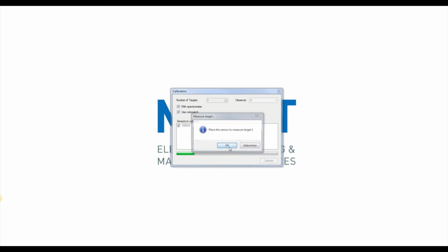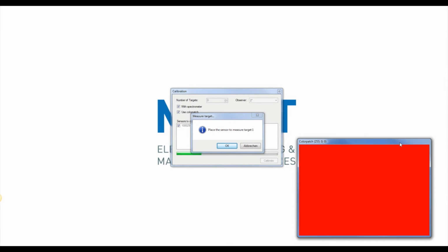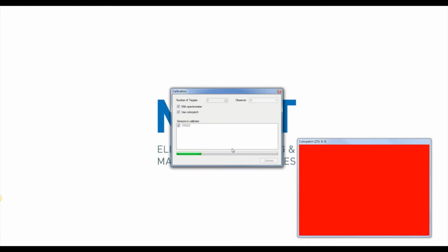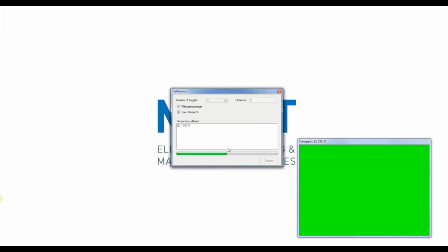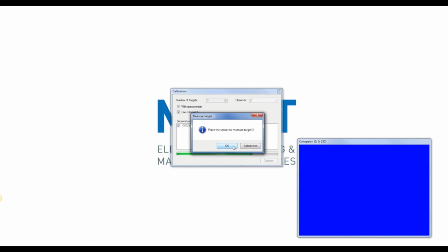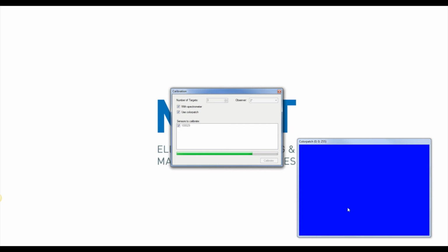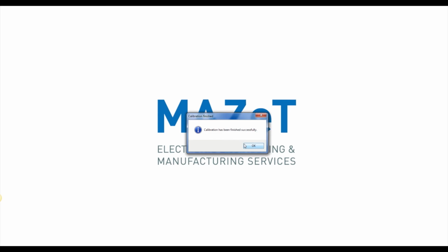The user can choose the number of calibration targets and start with an offset, a dark measurement. The following step is to measure the chosen number of targets. After the measurements have been performed, one needs to import or enter the XYZ reference values measured by the spectrometer. A data file with specific calibration information is saved and can be used for further reference.